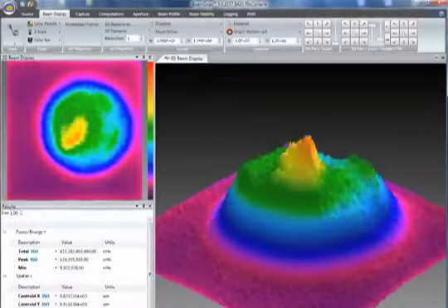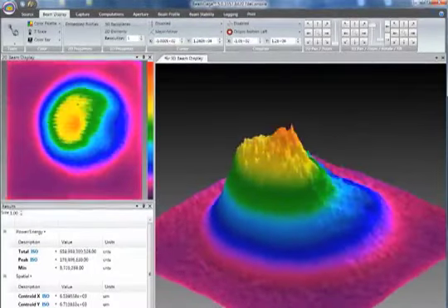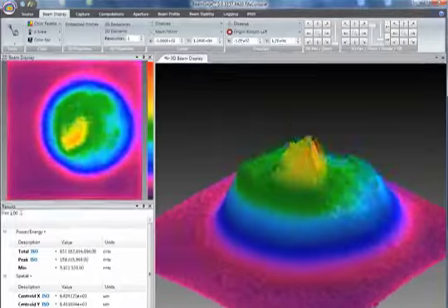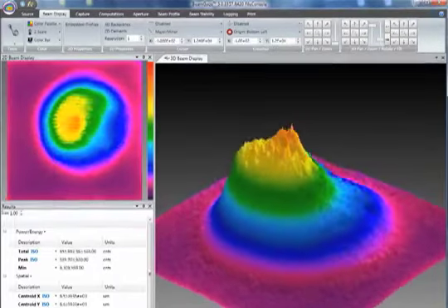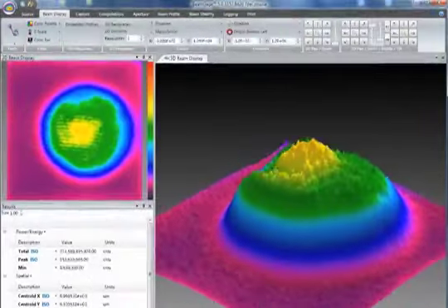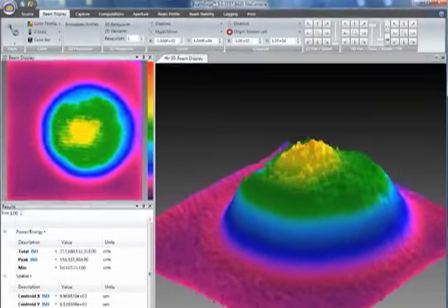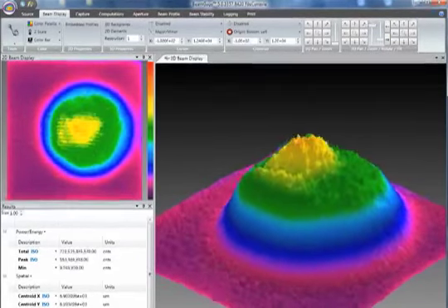This industrial 2 kilowatt CO2 laser beam produced poor welding joints. The Spiricon Pyrocam 3 beam profiler showed a highly asymmetrical beam. Adjusting cavity mirrors restored the beam in less than 10 minutes, eliminating downtime, scrap, and reducing cost per part.